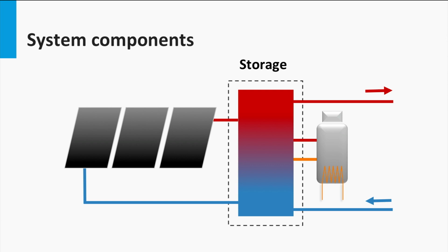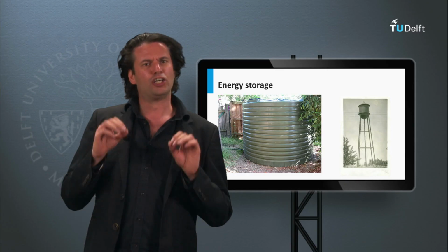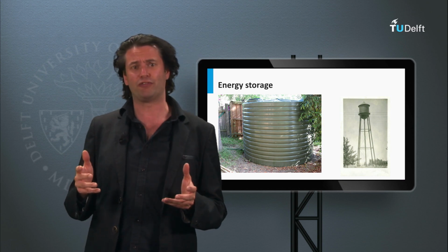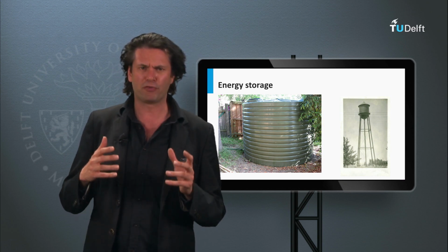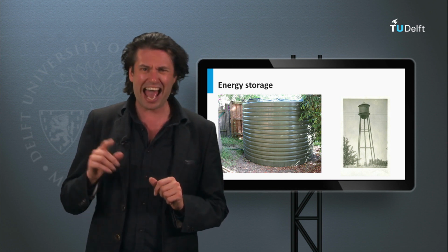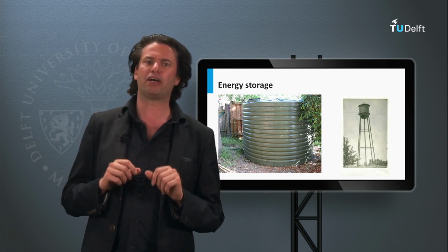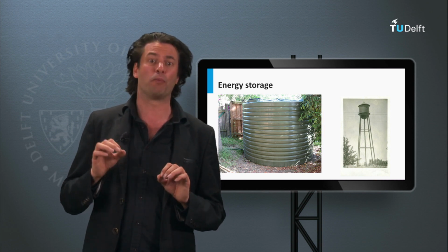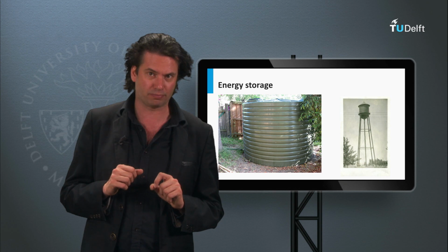That is why it's very important to choose the correct energy storage. Storage has mainly two functions: improvement of the utilization of the collected solar energy, providing thermal capacitance to minimize the load mismatch, and improvement of the system efficiency by preventing the array heat transfer fluid from quickly reaching high temperatures.